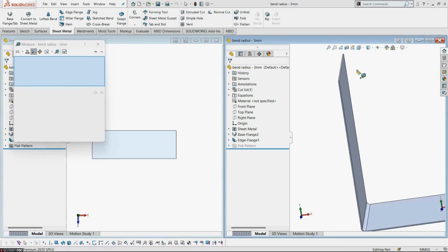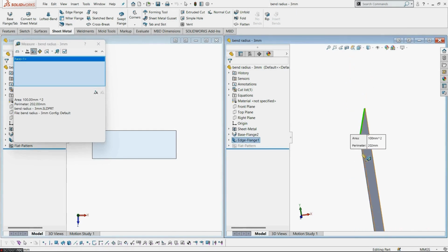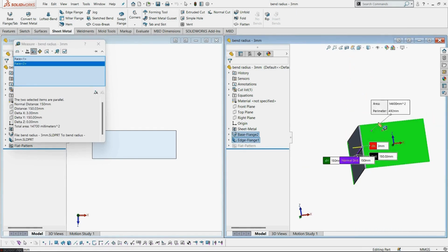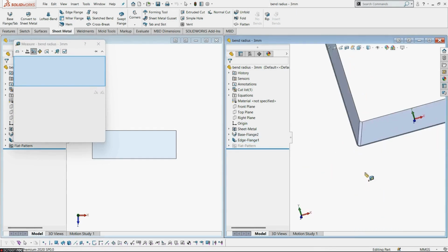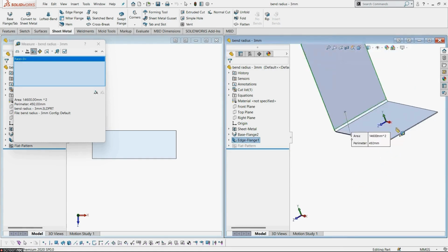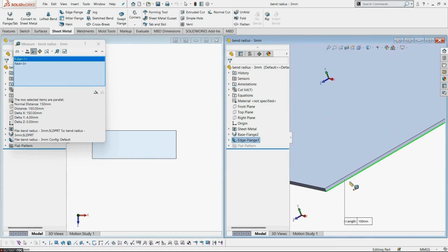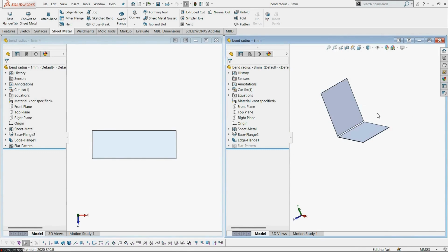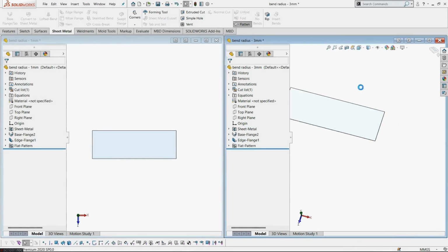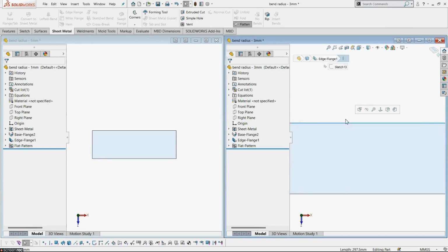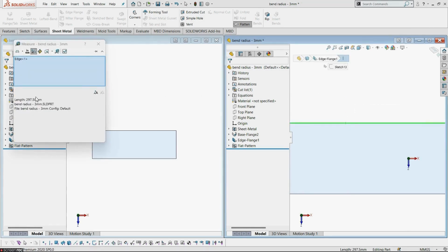Next one is solid modeling. Solid modeling covers not only the basic features like extruded boss, revolved boss, and pockets. It covers the advanced features like combine bodies and indent. It is not only important to design the product, it is important for separating mold features also. That is the importance of learning advanced features.